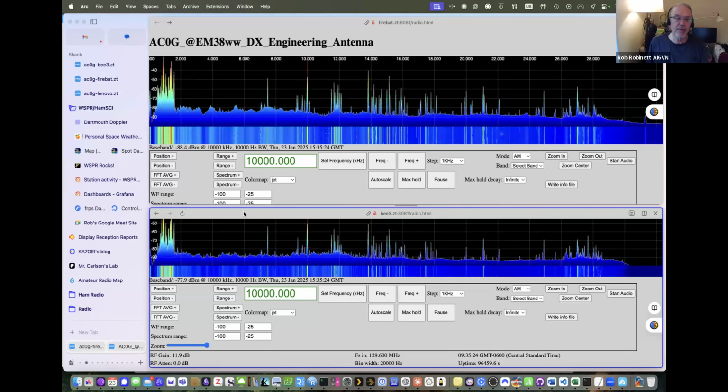Yeah, but even so, there are times when what you really need to do is, Clint, KA7OEI, has documented how you can suppress the emissions from any switching supply if you properly filter the inputs and outputs. You have to filter on both sides with something like a line filter like the Corcom, the 110 volt line or 220 line filter. So if you use those and put a switcher in a box, you can get them to be as quiet as a DC supply.